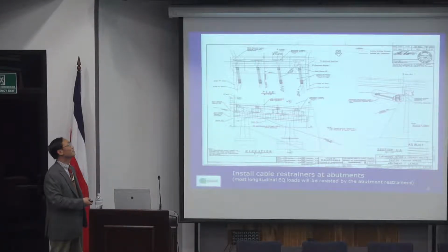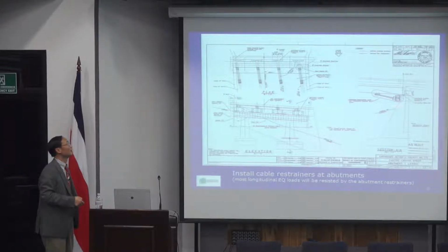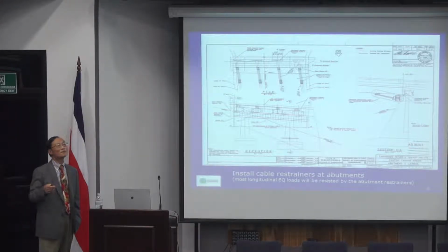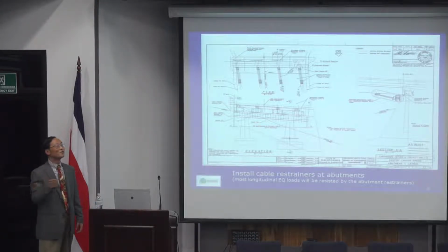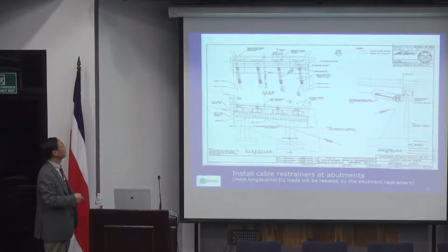The longitudinal movement is actually just tangent to the curvature, and also that will provide, because you cannot use a cable. Cable can only resist restrictions in one direction, so they use very rigid restrictions. That also restricts you from transverse swinging, because the transverse swinging effect is very significant for that heavily skewed bridge.